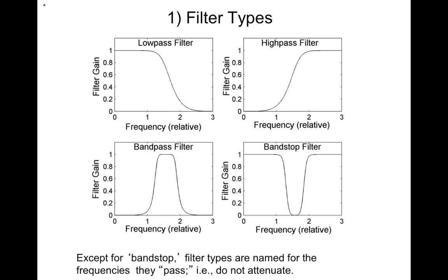Why would we want to use different kinds of filters? Turns out that a lot of times signal noise occurs either uniformly over all frequencies or will have more high frequency characteristics. So a low pass filter is often used to increase the signal to noise ratio and get rid of noise issues in the filter.